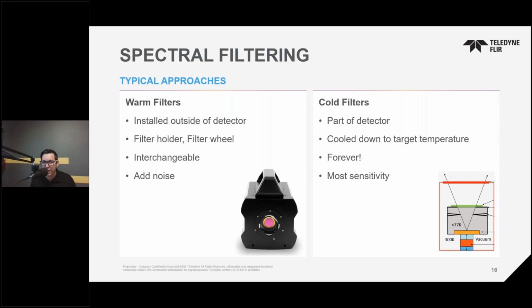Now, you can always crank up the integration time, or exposure time, so that you're capturing for a longer period of time, but it all depends on what kind of noise floor you're also going to add to that signal. A cold filter is going to be forever part of that detector. Most companies, most people will not attempt disassembling those, because you stand a high likelihood of damaging the overall detector and having to scrap it, and they're very expensive. So consider those purpose-built forever, but the best performance for those specific filtering applications. And then the warm filters, this is where you've got flexibility.